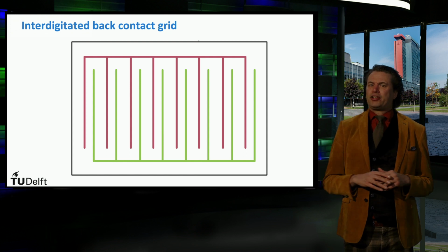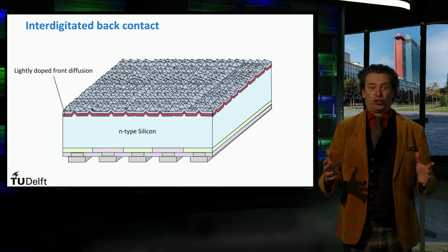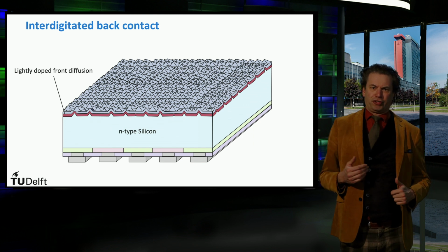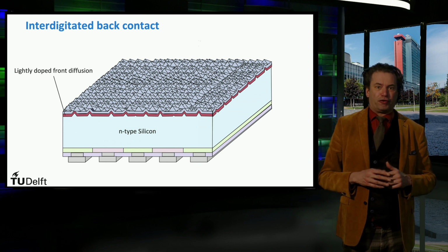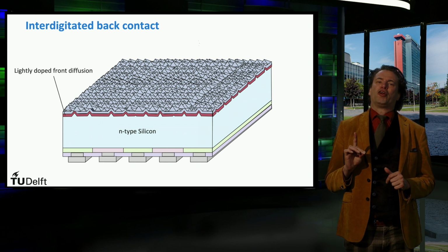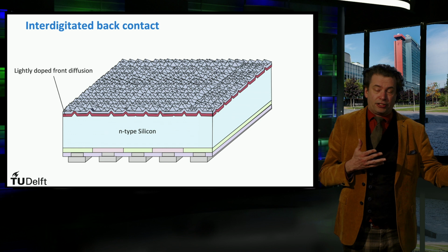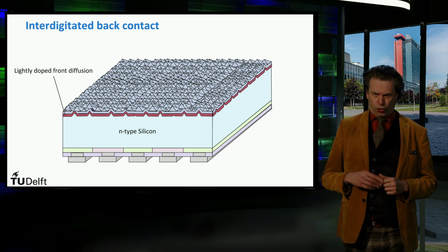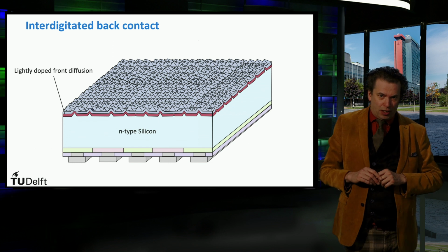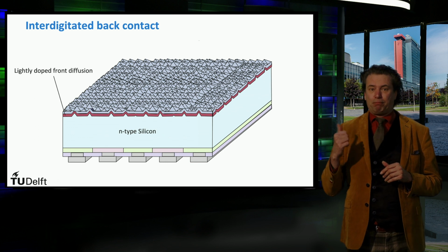At the front side, the losses of the light-excited charge carriers due to the surface recombination is suppressed by using the same tricks like the back surface field as discussed for the rear surface for solar cells based on P-type wafers. The surface recombination velocity on the front surface is determined by the minority charge carriers, in this case, the holes. Consequently, we have to create a front surface field. A higher N-doped region is placed at the front indicated by N+.